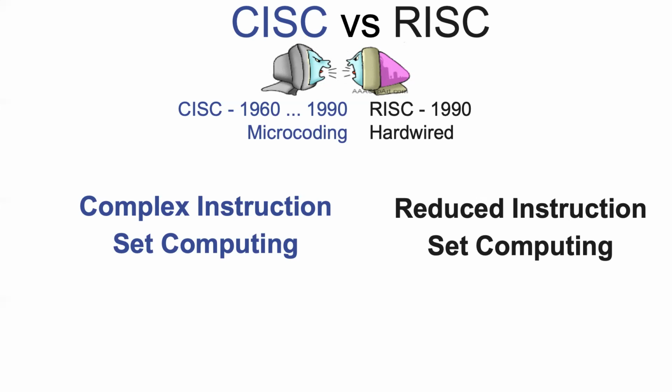And all of those instructions should be as uniform as possible. When I say as uniform as possible, I mean things like they should have the same encoding length. They should run in about the same execution time, or in the same number of clock ticks. And we've seen examples of each of these.